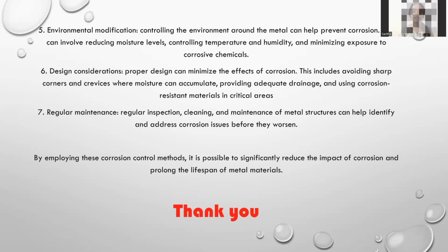Design considerations. Proper design can minimize the effects of corrosion. This includes avoiding sharp corners and surfaces where moisture can accumulate, providing adequate drainage, and using corrosion resistant materials in critical areas. At last, regular maintenance. Regular inspection, cleaning, and maintenance of metal structures can help identify and address corrosion issues before they worsen.